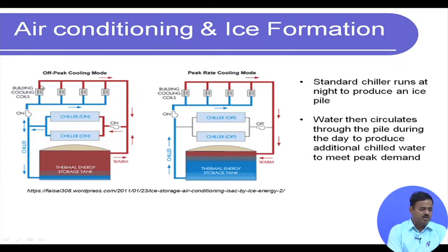Okay. So, then the chilled water as it comes out of this heat exchanger or of this evaporator unit is now at a higher temperature. It comes back, is pumped again into the chiller units, where you have actually refrigerant that cools the water down.